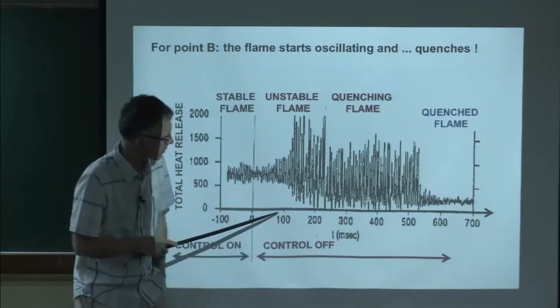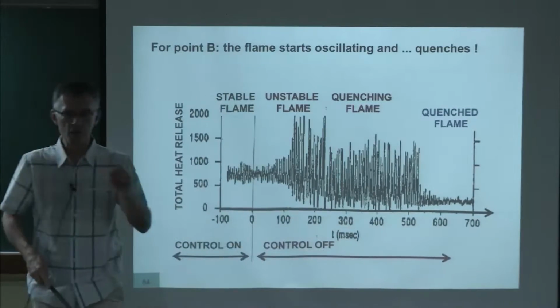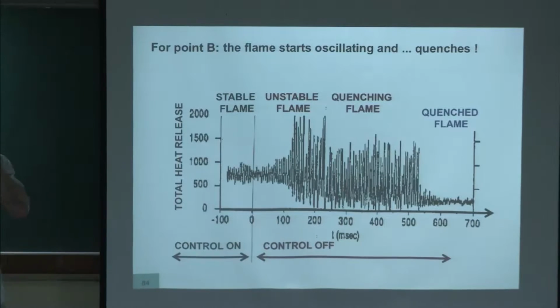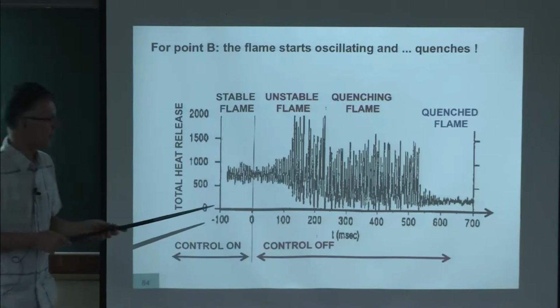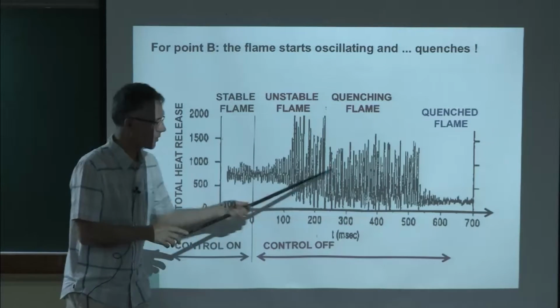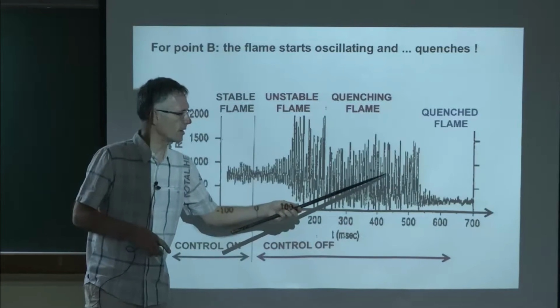It doesn't take long, okay? It takes half a second. So if you sit in front of the experiment, you don't hear anything. Half a second is not long enough. So you just say, oh, my flame is quenched. No, actually, the flame is not quenched. It goes unstable, and because of the instability, it quenches.